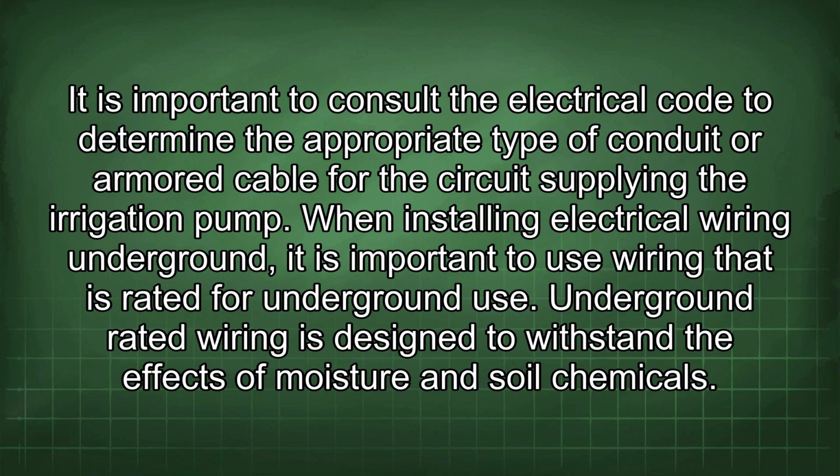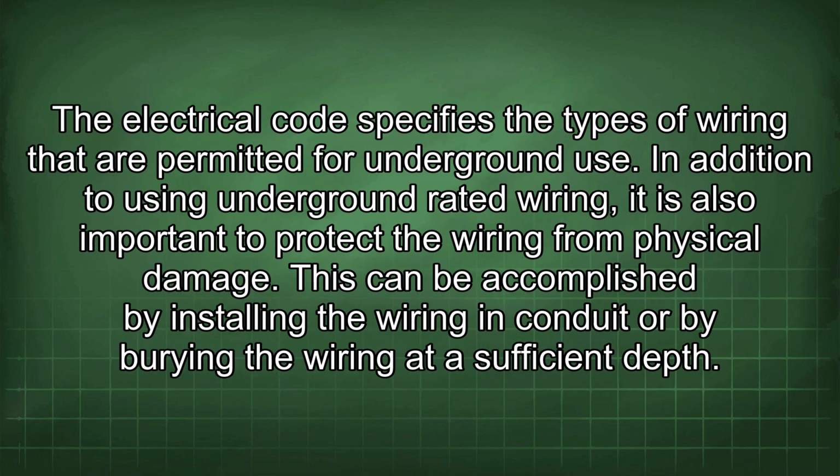When installing electrical wiring underground, it is important to use wiring that is rated for underground use. Underground rated wiring is designed to withstand the effects of moisture and soil chemicals. The electrical code specifies the types of wiring that are permitted for underground use.